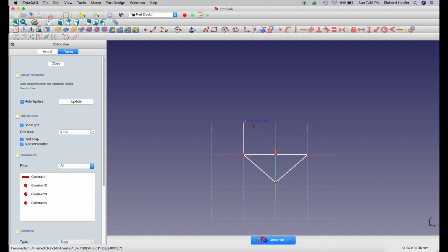Then enter your capital H value into the grid snap box and make a 90-degree line from the point we just made to the first positive grid line in the z dimension. If you are using a value of capital H which is not equal to s or a multiple of s over 2, make sure there is a straight vertical line constraint when you make this line, otherwise this face will not turn out correctly. Next, we will repeat the same procedure for the other side.